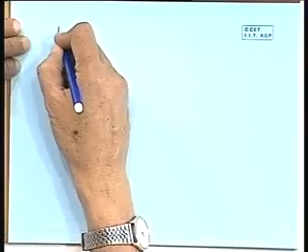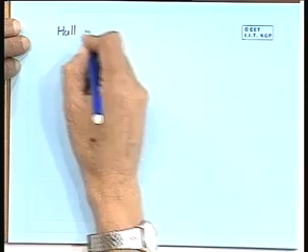So, once we are giving that specification, we are restricting ourselves to use of that particular RPM, and therefore, we have to be very careful and find out which RPM is acceptable to us, and that is why these formulas come very handy to estimate the frequency level and find out which RPM is acceptable to that particular design ship. Now, for that we go for what is known as hull resonance diagram.